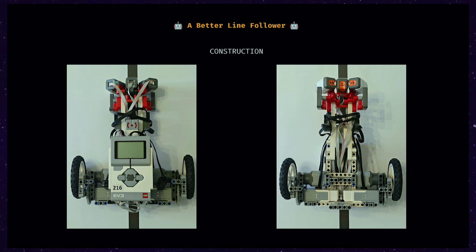And if you look below, you can see the sensors, but you can also see that it has 2 motors per wheel, which is a bit strange. This is because I wanted to have encoders to know the speed of the motors and the length traveled and everything. But these motors that have the encoders just don't work in races. They are too slow. These are proper motors that actually do work with races. They are directly connected to the wheels. And the other ones just help on the side without slowing the thing down, and essentially I use them only for the encoder. But, well, it actually worked out pretty well.